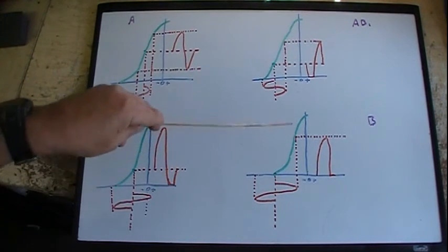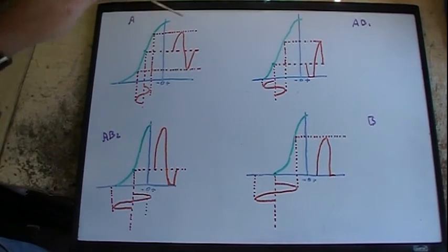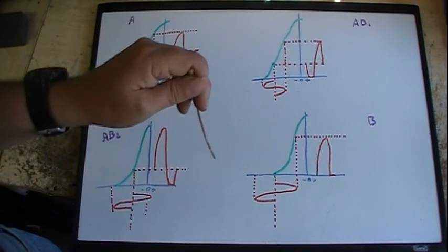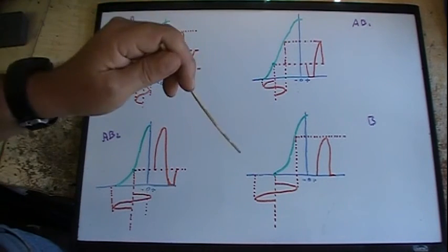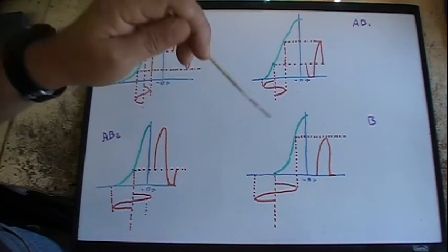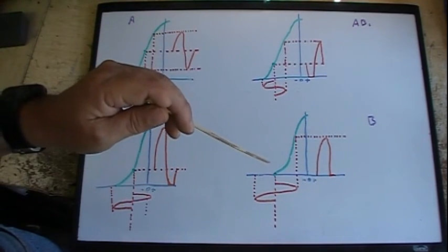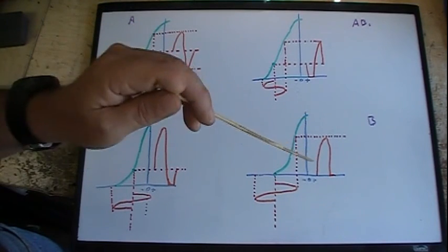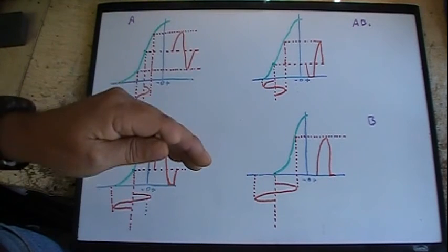One thing I do want to point out: a good operating push-pull amplifier, no matter what class it's in, has almost no even harmonic distortion, because the output transformer cancels it out. It will cancel when it hits the primary of the output transformer. So there is no even.